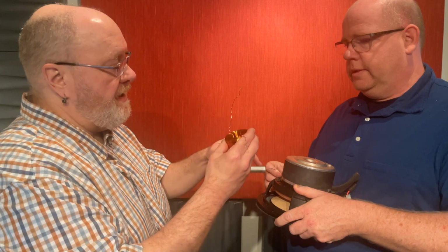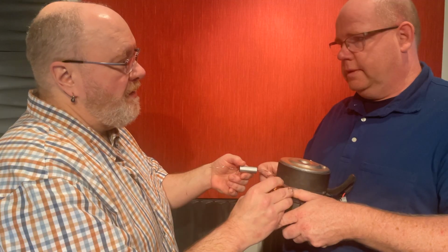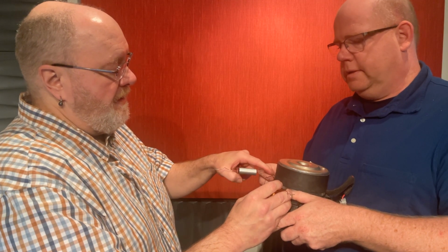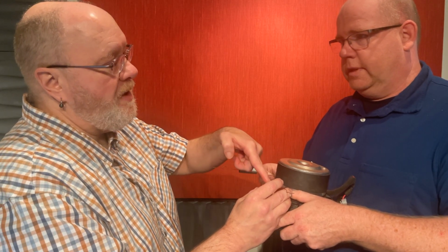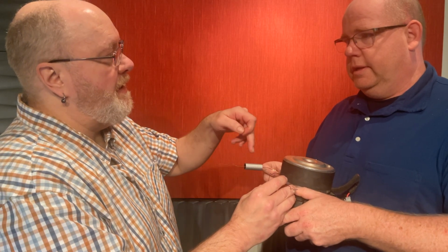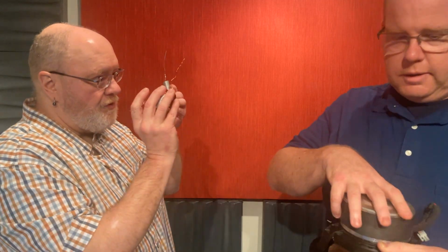And if you match these two to where they're working in the same frequency band, and you put this one in front of that one in parallel, you get 6 dBs here. Then it comes out here, and then it shunts off highs here or lows here as well. And you get shunt off, so you get 12 dB per octave slope. That's why I get the second order. It's second order because there's two filters in line.